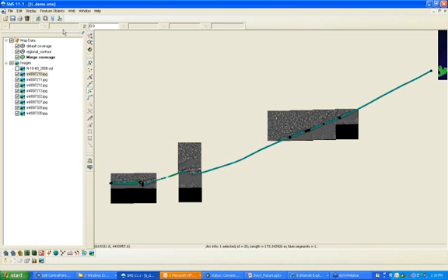So now I'm going to go ahead and enter my wave gauges. And I'm actually just going to enter 3 points along the shore. And in this case, I actually have the XY coordinates of them, so I can just enter those in. So I will click on each of these wave gauge locations.